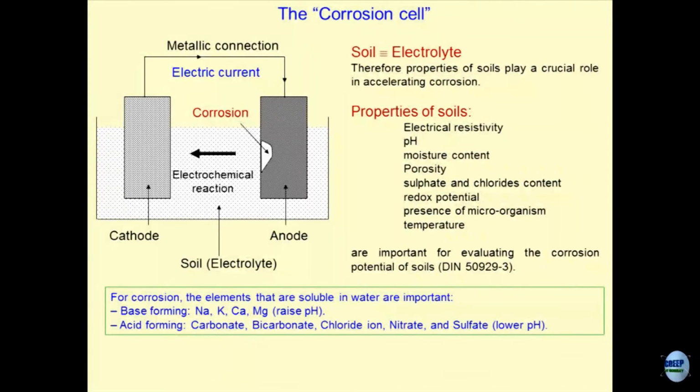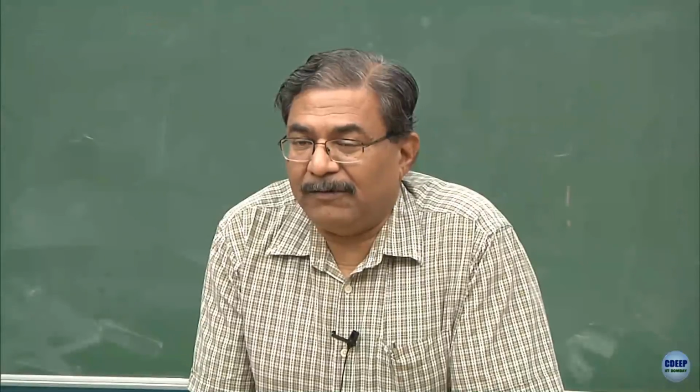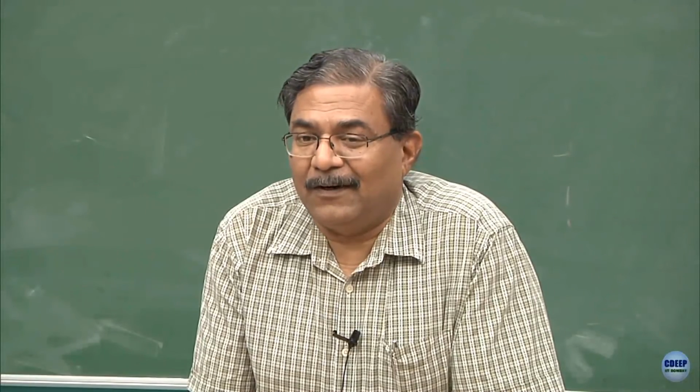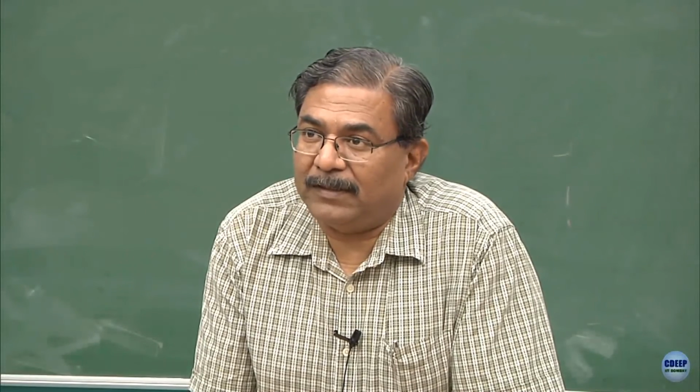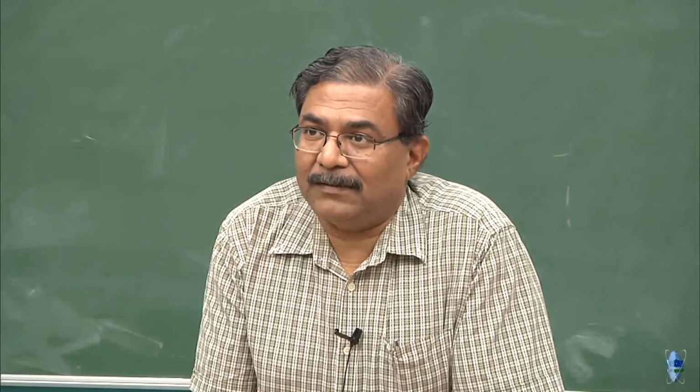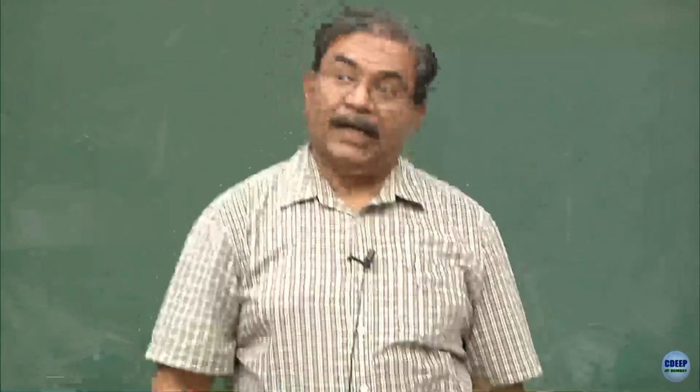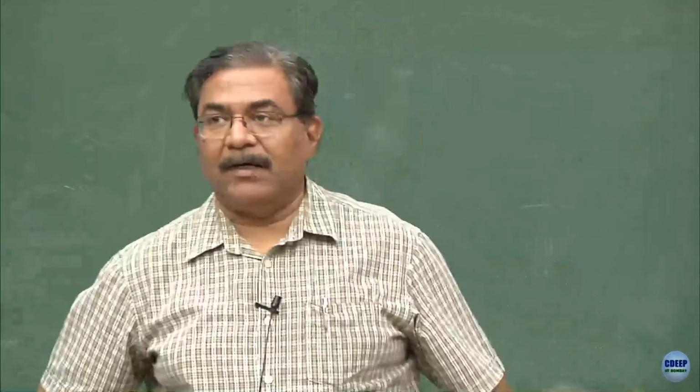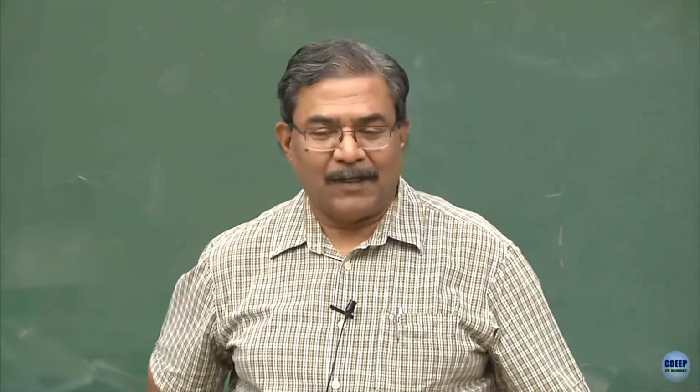Why not? Yes, isolation is a very good solution. We do base isolation against the earthquakes. Please remember, all these structures you are designing for several years, and our pretext was that all these systems are directly exposed to the environment. Look at the coastal areas. How would you protect your foundations against the seawater intrusion? Check it out on the net, what type of disasters have occurred because of the corrosion of the material, and then you will realize how many buildings have collapsed. Yes, it is not a small thing.